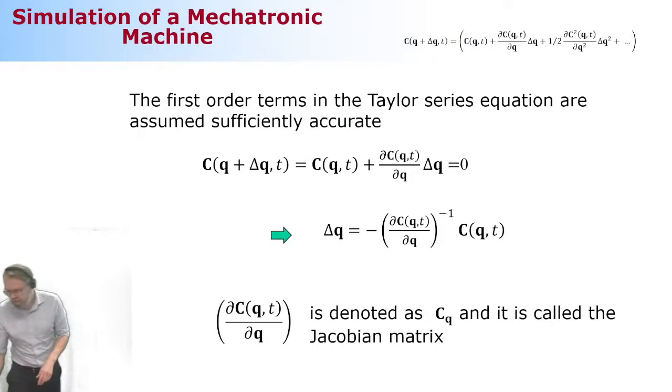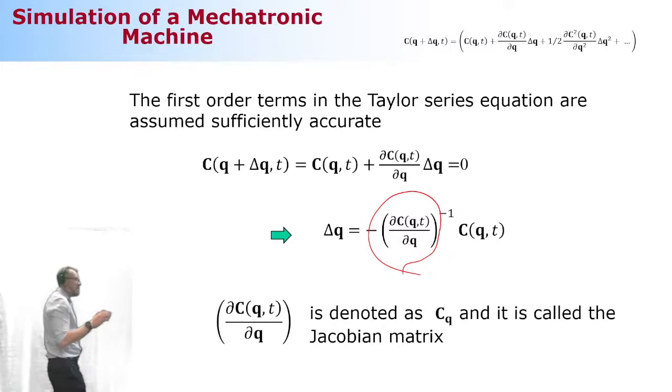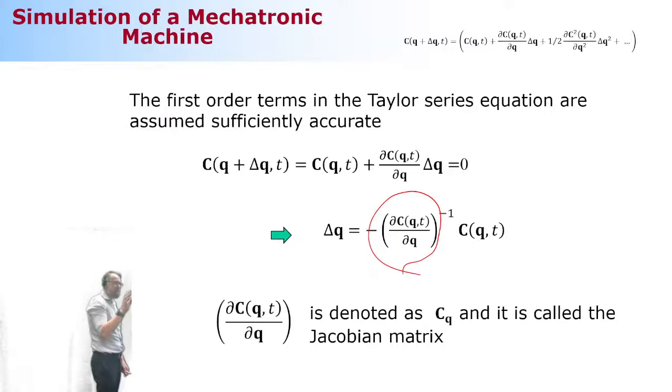This guy here in the middle is the Jacobian matrix. It's a very mechanical thing. You take each of these constraint equations and differentiate them with respect to each of your variables. It's very handy to do using a symbolic math tool, and a big pain to do with pen and paper. Don't use pen and paper.